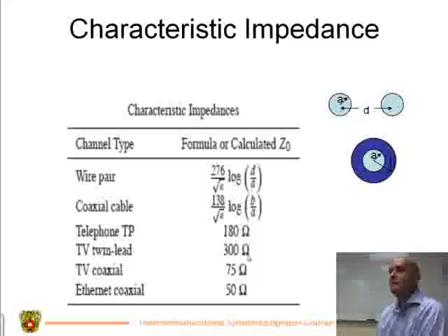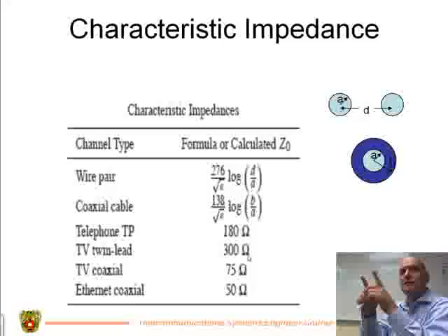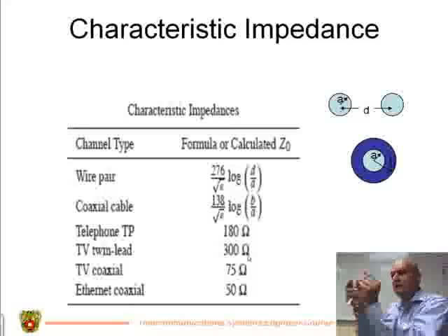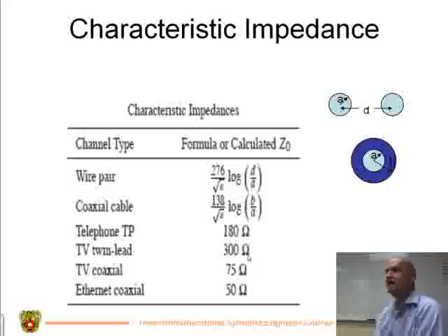Length of cable doesn't matter. It's just that type of cable. If you had a cable with a big flat connector with two little conductors in the sides, and two little screw-on spade connectors on the end, that's a 300 ohm cable. Because the A and D were known, somebody figured it out, and it turned out to be 300. This is not about overall loss like dB over length. This is about the impedance matching of that cable. Coax is typically 50 ohm.